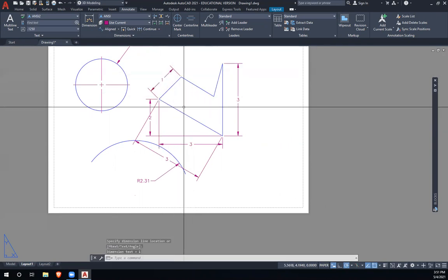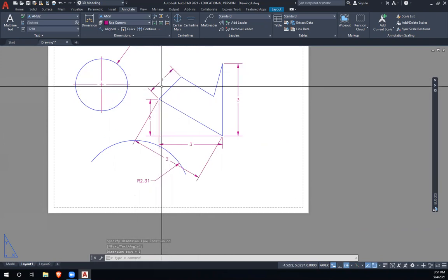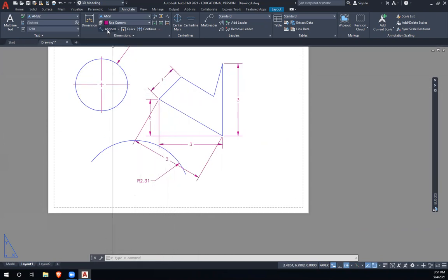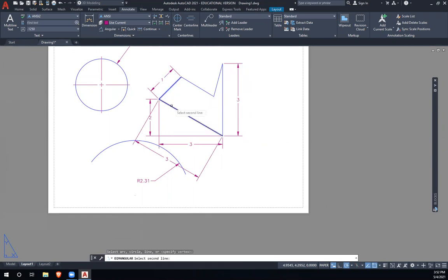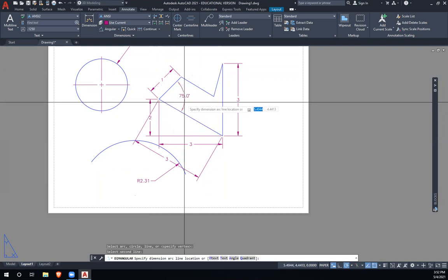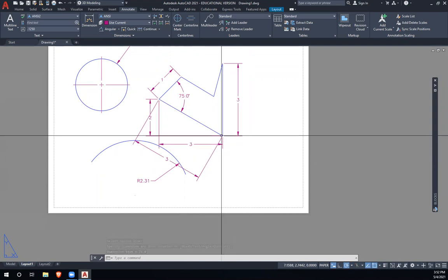Here's an align dimension, but that doesn't help much because I don't know what angle that is, but maybe I want to dimension it with an angle. Right, so let's see how an angle works. Angular dimensions need 2 corners, right? So maybe this end and this line and that line, and it'll give the dimension between them, or the angle between them.